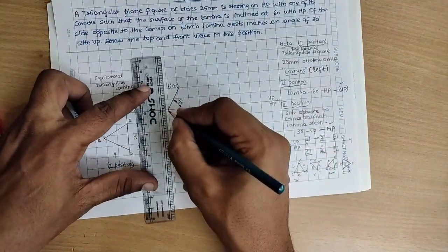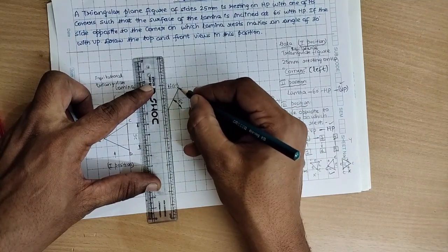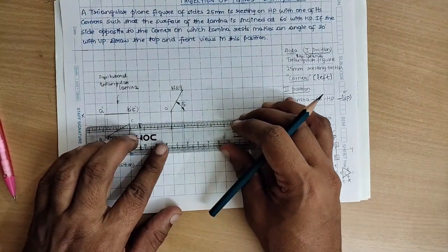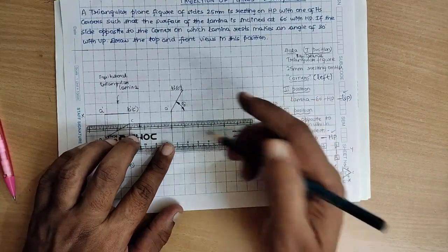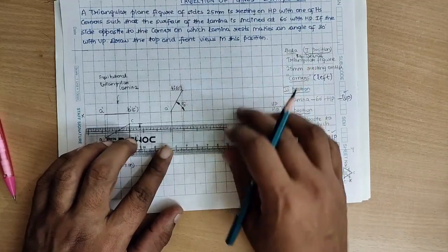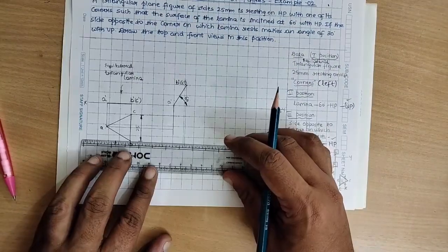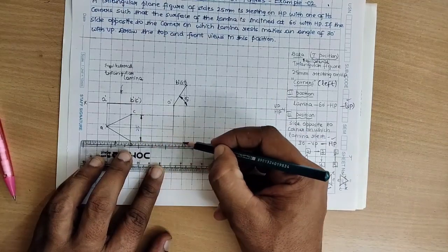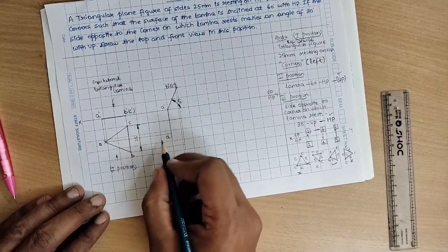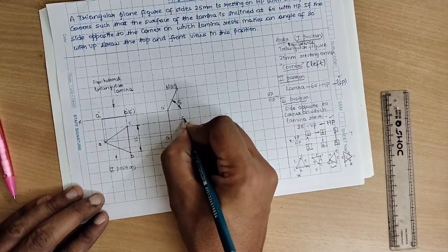Make use of projection line. Projection from this point, projection from point B and the C. Similarly, go for the horizontal projection. Projection from point C. It touches the previous projection line what we have drawn. Similarly, projection from the point A. Also the projection from the point B. Projection from point A and A both are intersecting at a point, represent it as point A. This would be the point B, similarly followed by point C.